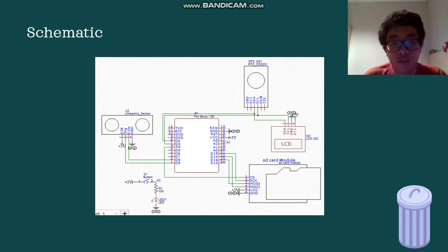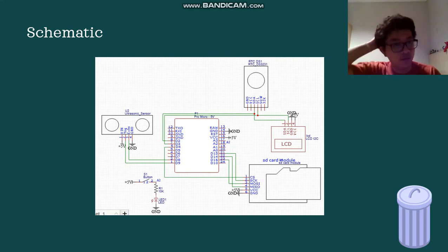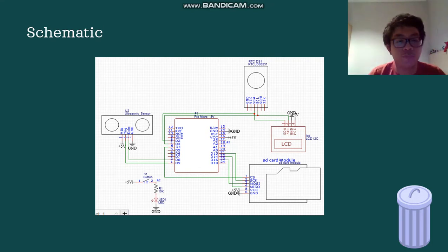So this is the resulting schematic. You can see the pin functions. Basically every pin has its own functionality. The SPI is pins D14 to D16. The I2C is pins D2 and D3, and so on.